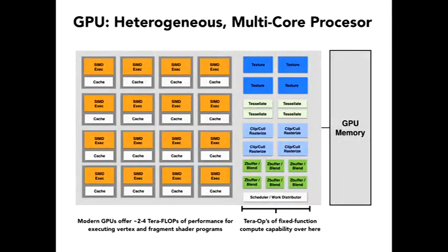That design is for computational efficiency, not because that's how the physics works or how the light will really transport in the real world, but it allows us to write for a huge number of SIMD, or think of these as compute units, huge numbers of parallel compute units that just get interpolated values in parallel from lots of different samples, compute the same shader program repetitively on each one of those, and flow the whole thing through, okay? So that's one way to think about how GPUs have organized not just their architecture, but at the same time they've organized how we think about and write graphics programs for a long time in order to fit well to this compute.